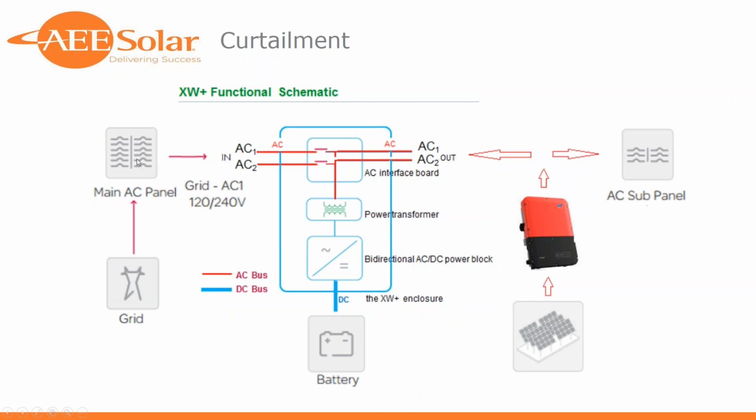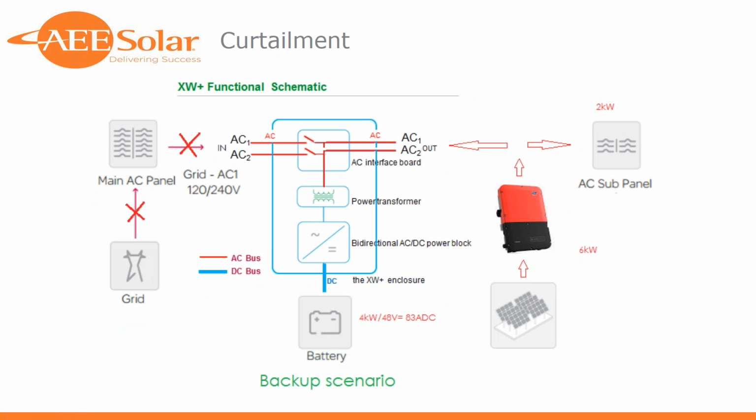So really what we ended up doing there is similar to what we have here. Grid, AC panel, well, no grid, but AC panel with loads, inverter charger, battery, PV inverter from array, AC sub panel. When the system is curtailed, when the grid is down and there's no power from PV, you're still sending a qualified grid signal to, in this case, the Sunny Boy inverter. In curtailment, you're tweaking that signal that the PV inverter sees so that you can operate at 80% of rated power or 60%. SMA really got onto this first. They had for a long time on their Sunny Boys, and they may still, a mode called basically off-grid mode. What this did was disable the 5-minute count up on 1741, and it would take inputs outside of that standard 60 hertz.